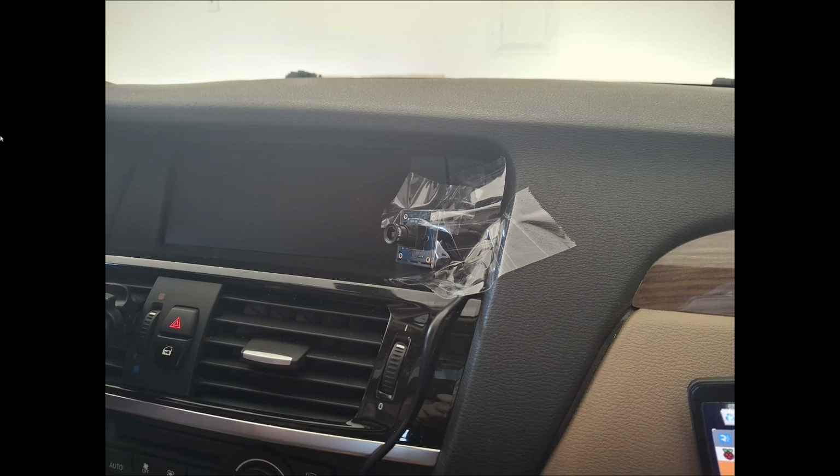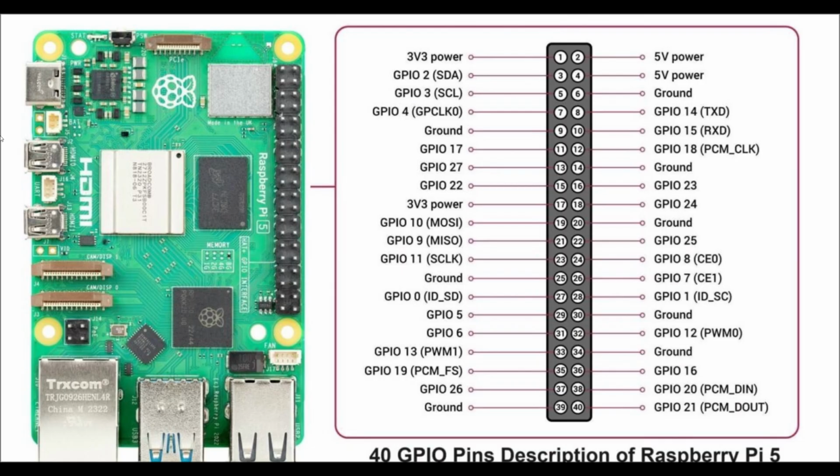The USB camera connects directly to one of the Raspberry Pi's USB ports. Because it's a USB camera, the Raspberry Pi automatically detects it without extra drivers. That makes USB cameras very easy to use compared to CSI cameras. This command checks if the camera is detected. If I see /dev/video0, the camera is ready to use in Python with OpenCV.